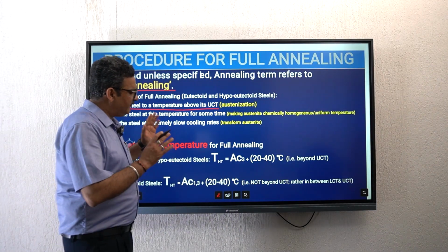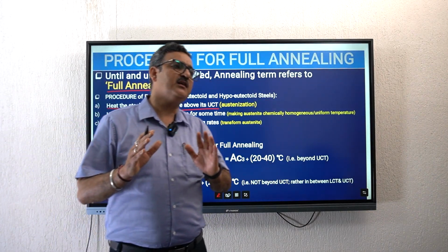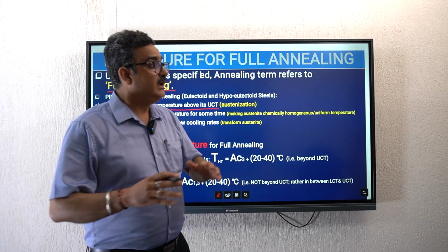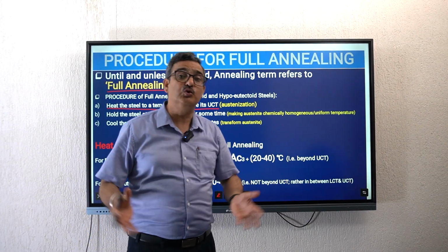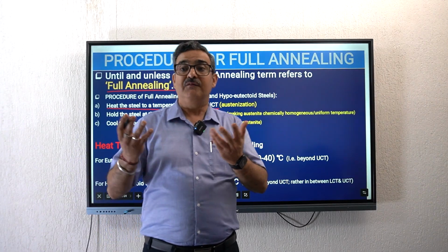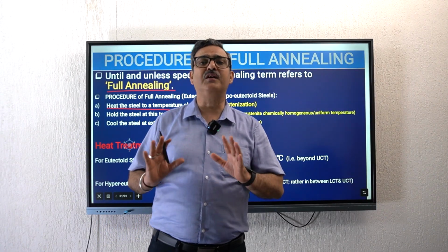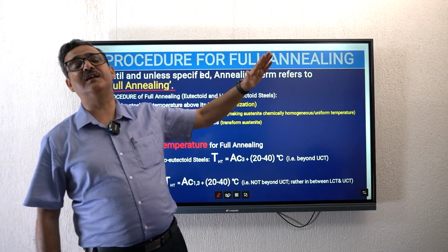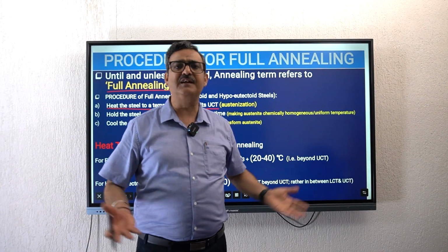So if the steel has not been cold worked before it is brought for heat treatment, if the steel is not containing a huge amount of internal stresses when it has been brought for heat treatment, during heat treatment you can use as fast a heating rate as you wish to, as your facilities permit.